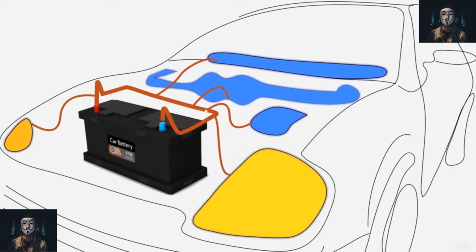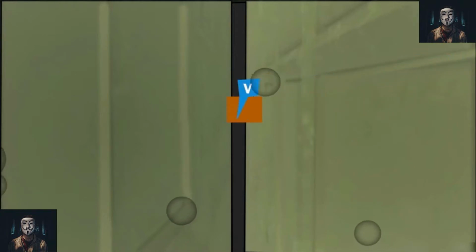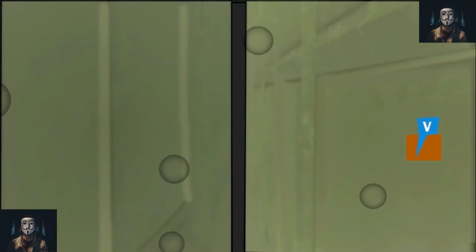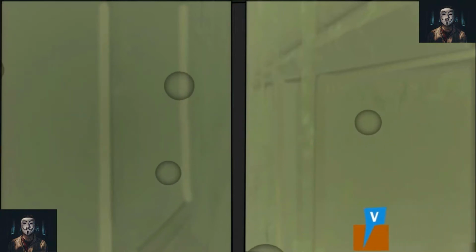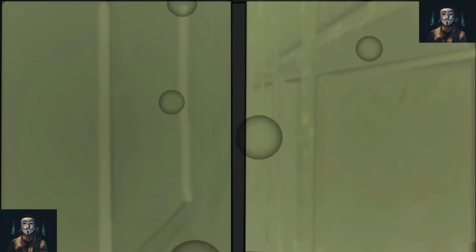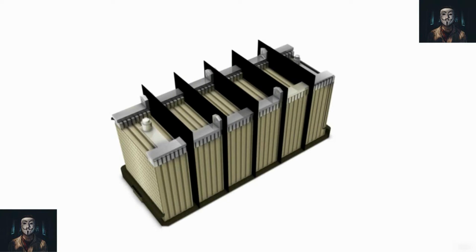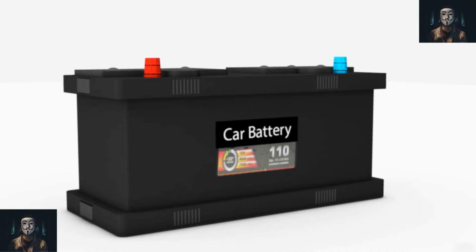the battery. The hydrometer is color-coded. A green color indicates that the battery is charged and serviceable. A green-black or black color indicates that the battery requires recharging. A yellow color indicates that the battery is faulty. Where a yellow hydrometer is showing, the battery should not be recharged or tested, and the use of jump leads for starting should not be carried out. A new battery should be fitted and the alternator checked for correct operation.